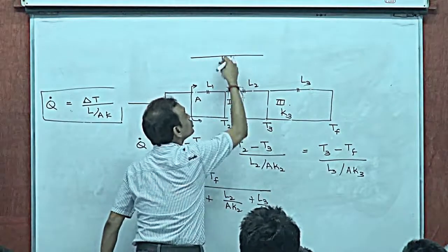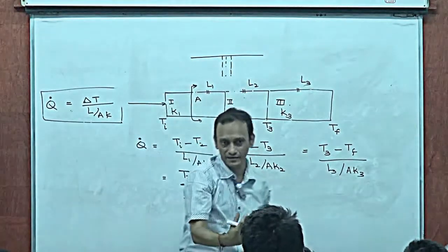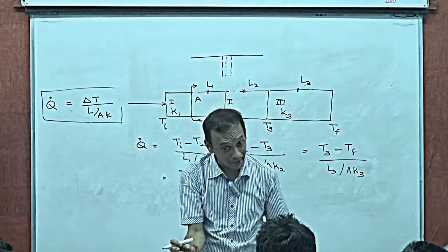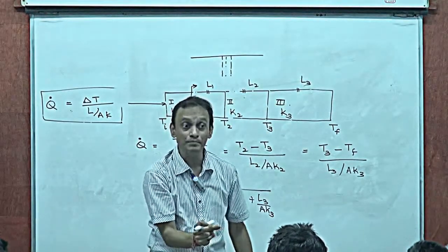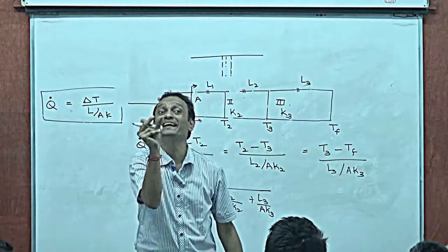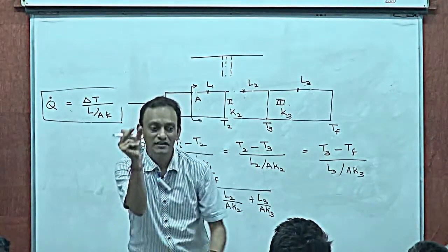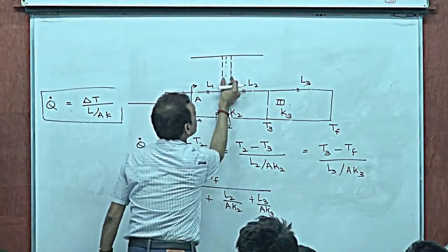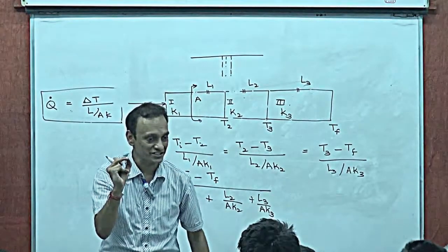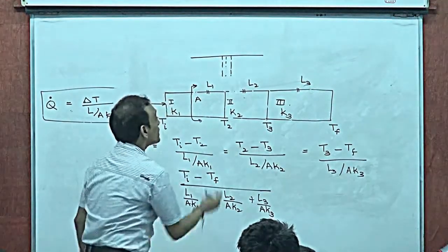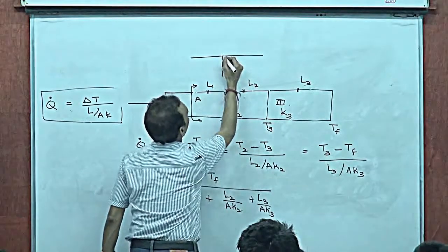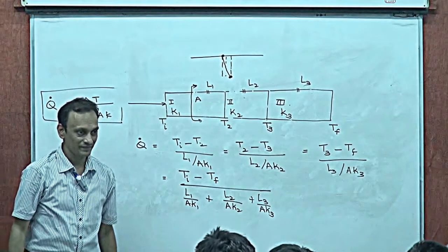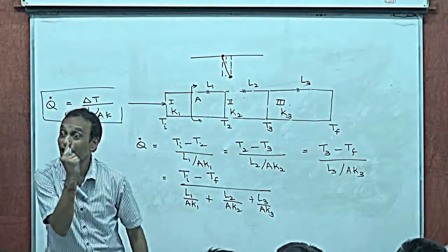That means across this air gap, which you can't see when you're imagining that it's perfectly pressed. But realistically, it could be an air gap, for example, or maybe it could be an adhesive gap. There could be an adhesive which might show up as a small thickness, right? So then, that by itself will offer thermal resistance. And if that offers thermal resistance, then at the interface, the temperature would drop. So there is a contact resistance.